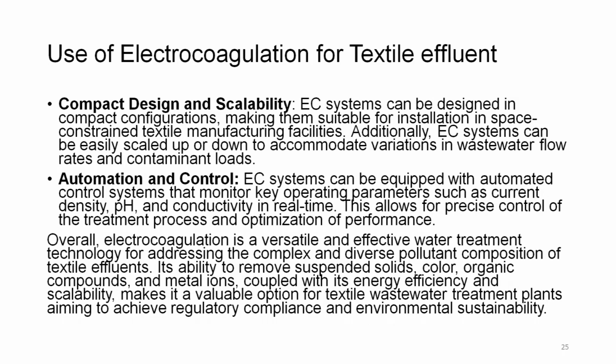Overall, electrocoagulation is a versatile and effective water treatment technology for addressing the complex and diverse pollutant composition of the textile effluents. Its ability to remove suspended solids, color, organic compounds and metal ions, coupled with its energy efficiency and scalability, makes it a valuable option for textile wastewater treatment plants, aiming to achieve regulatory compliance and environmental sustainability.